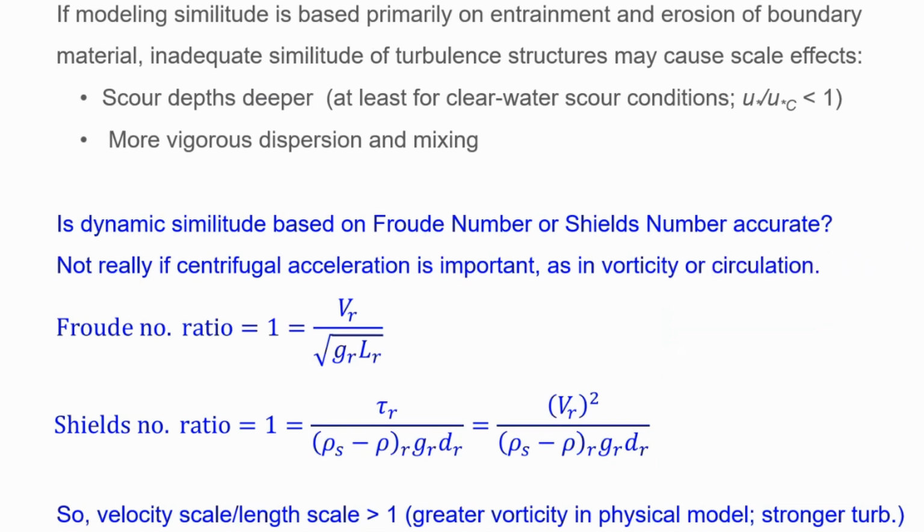So you've got to be very careful. I wonder sometimes whether Froude number is appropriate for modeling vortex flows, drop structures and so forth, where you deliberately set up a vortex flow, because you're exaggerating the vorticity of that drop structure. I'm not sure that the lab models capture what's really going on in that case, the structure design.